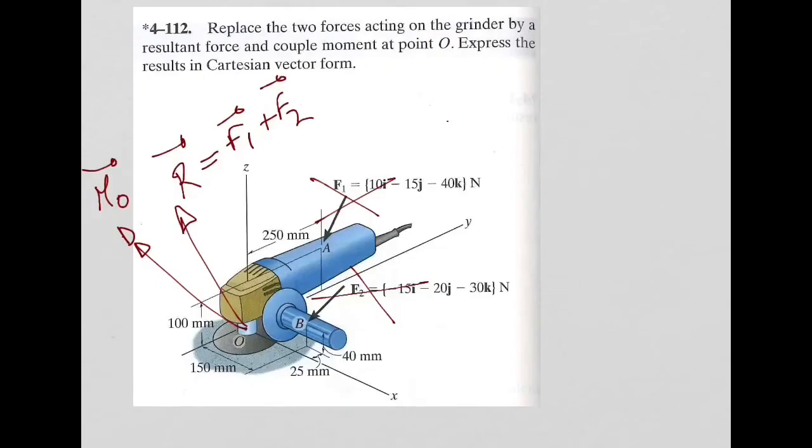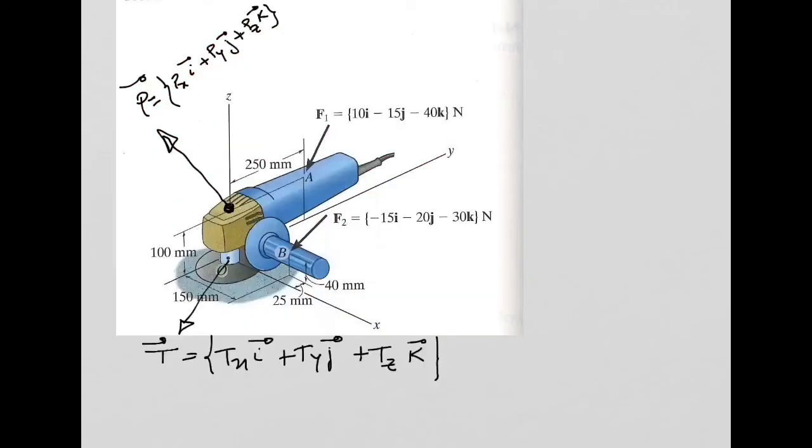What I'm doing now, by changing this problem, is I'm including two extra forces at different points, and I don't know the value of these forces. Right? I said force P has components Px, Py, Pz, which I don't know. And I also had a force T with components Tx, Ty, Tz, which I don't know the value of either. And I'm adding these forces so that I can restore the equilibrium of the system.